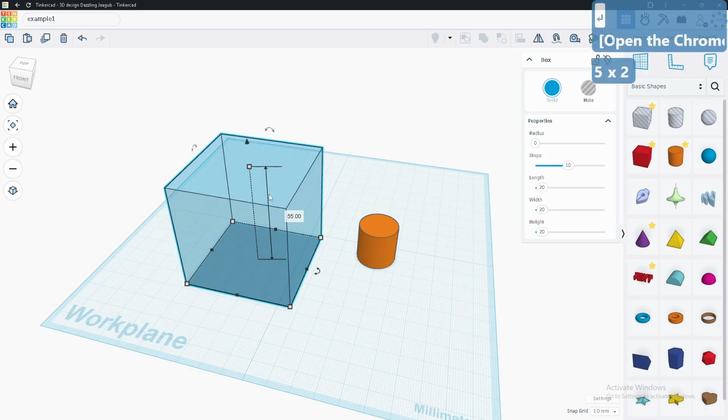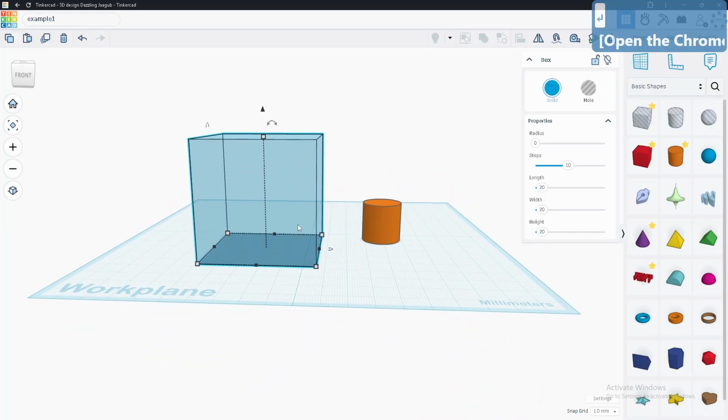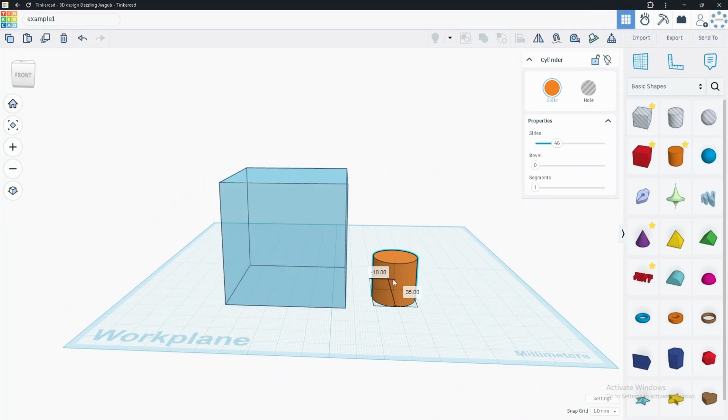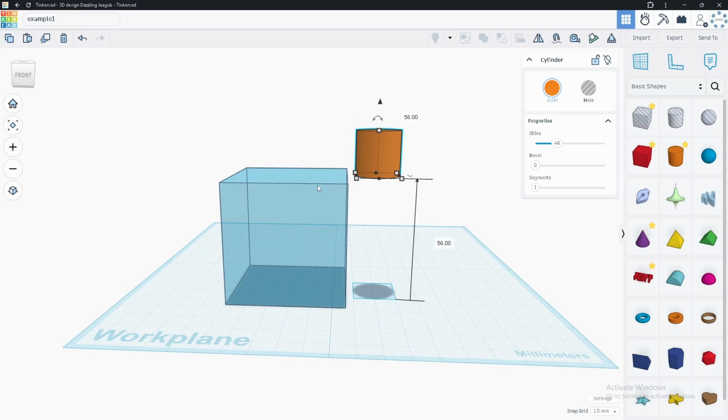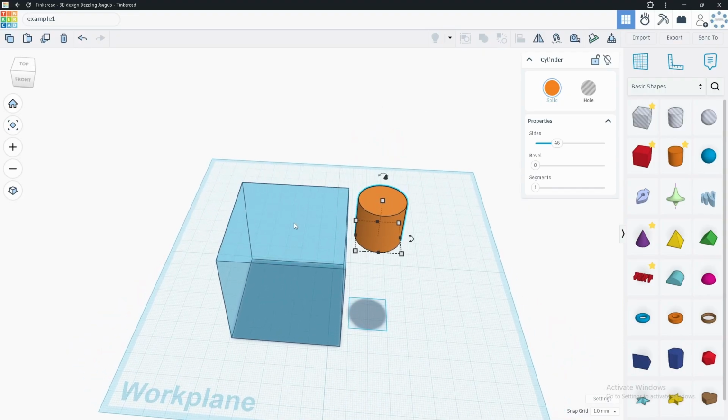Now, if you wanted, you could put this particular shape on top. There is a cone on the top of every shape, and you can drag these cones and you can lift your shape. Notice now there's a shadow down there. Let's lift it up again. Notice on the right side here, there's a measurement that shows me how high I've just lifted this shape. And now it's up to 50. If I go up to 55, I should be at the top of my blue cube. And I can just click and drag this.